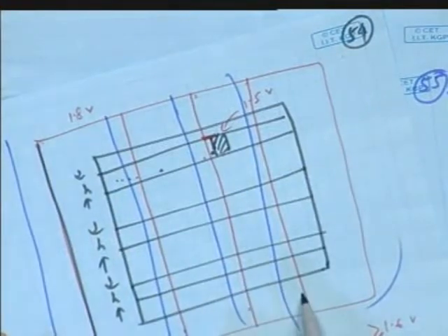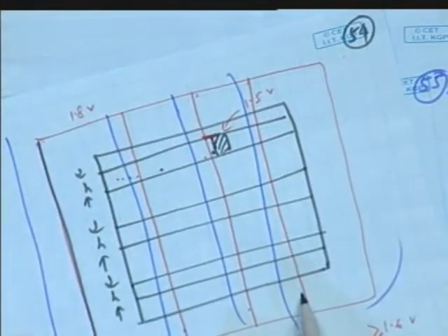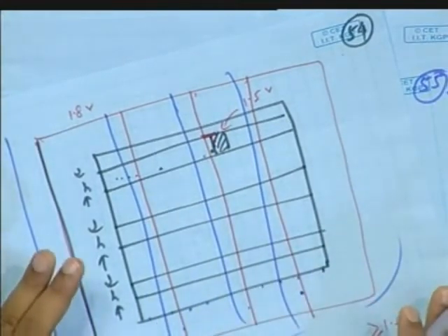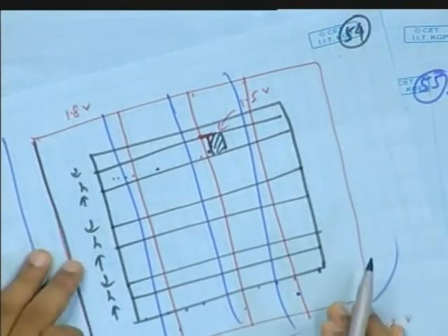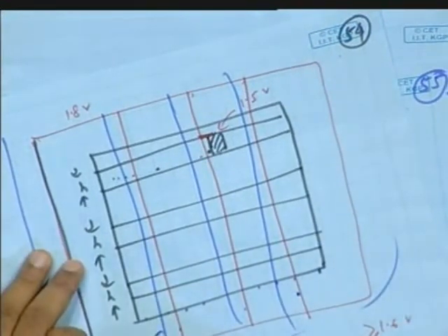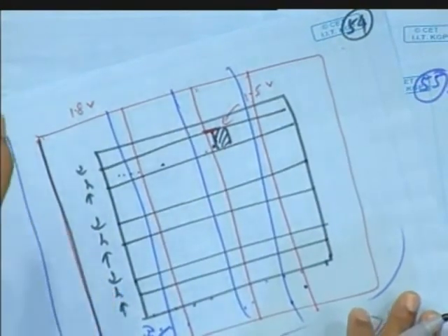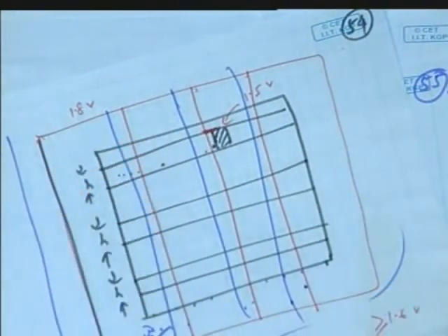No, wait. You say I define only 3 wires to be in your stack. And how many vertical lines can I have in a metal wire? Say 100. Now it is up to you whether these are my ground straps, whether I am using only 3 and I won't allow anybody to use other layers. Now his question is that if you do not allow, you are on the safe side. You are reducing the effect of interference. There is a term called ground bounce, all that stuff, power bounce.